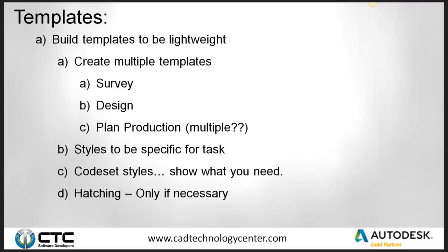Finally, templates. Build your templates to be lightweight. Create multiple templates. Have a surveying template. Have a design template. Have a plan production template. You may even have 2 to 3 design or plan production templates. And in doing so, you're going to have styles that are specific to the task.